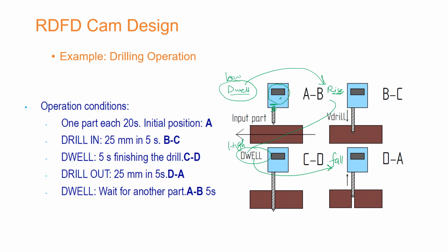The other thing that you should also realize is that if you force this drill to go quickly or abruptly downwards, there is always this chance of accident over here. So you have to carefully bring the drill downwards. So I'm going to write down over here: carefully.